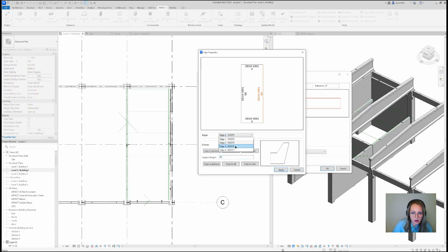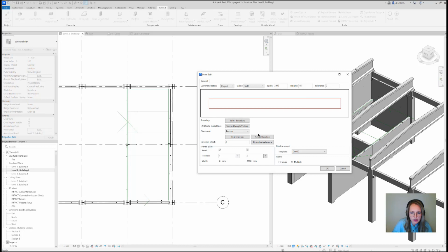It means that the slabs are going to go further 60 millimeters inside my panel thickening and relatively the massive wall. So I'm going to do the same here. What do I have? So it's symmetrical geometry, and for the 4 I was going to add 60 and 3001. Okay, I think it looks okay, this one. You can also change the direction, add elevation offsets, add a reinforcement template or remove it. It's just up to you.